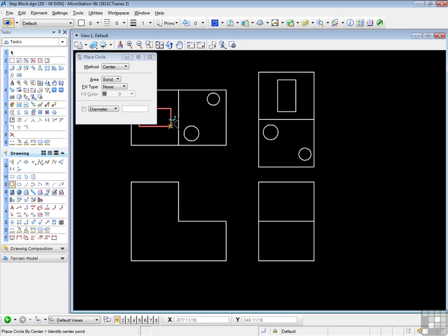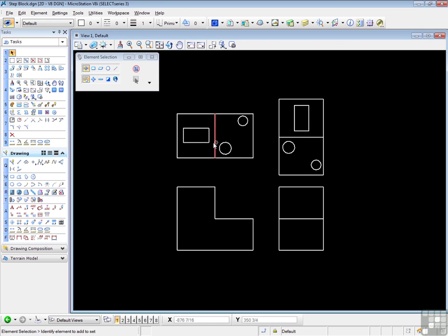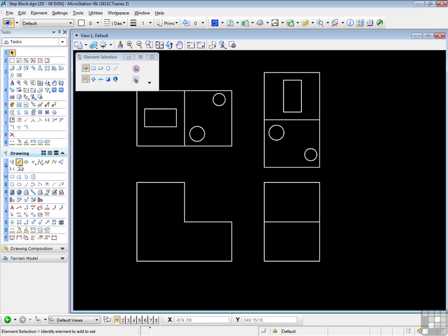Now see what's happened. As soon as I enter information in the top view, the same information shows up in the reference of the top view. Now that's interesting, and that's obviously extremely useful. So anything I do in this view automatically shows up in this view. And this is really what self-referencing is all about. If I delete the rectangle, it's deleted in the reference as well. Let me undo that. Back in again. So very powerful.